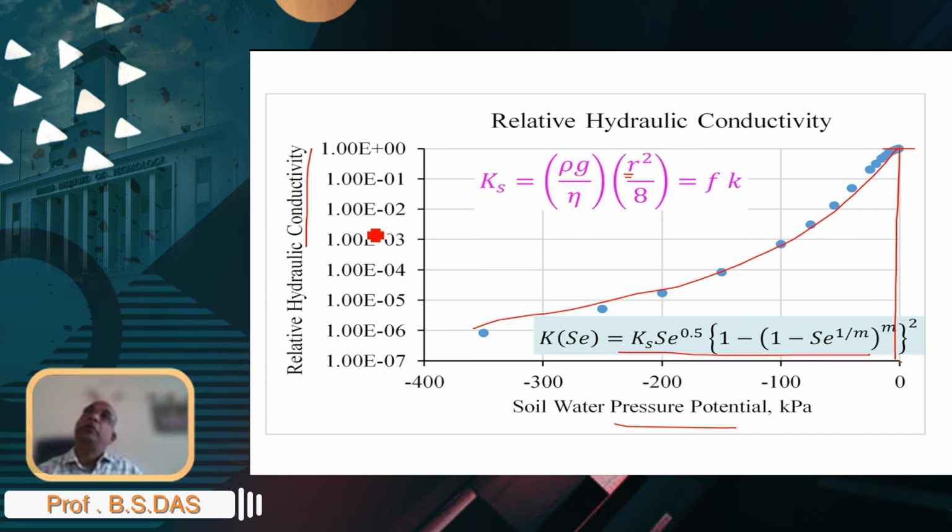So this is again the second soil hydraulic property that you come across in addition to the water retention behavior, right? Water retention characteristics and hydraulic properties of unsaturated soils are the two primary hydraulic properties of soil that you need to really understand, and quantification must be done so that you will be able to describe the water flow, whether in terms of Darcy's equation or in terms of the Darcy-Buckingham equation, right?